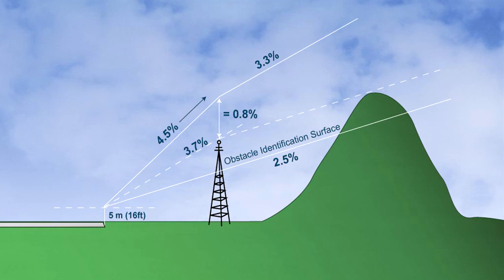Published gradients will be specified to an altitude or height, after which the minimum gradient of 3.3% is considered to exist. The final PDG continues to exist until obstacle clearance is ensured for the next phase of flight, en route, holding or approach. This is when the departure procedure is defined to end. The minimum obstacle clearance equals 0 at the departure end of the runway, DER, and thereafter increases by 0.8% of the horizontal distance in the direction of flight, assuming maximum divergence of 15 degrees.